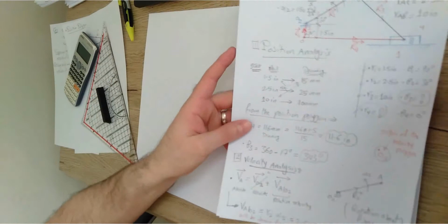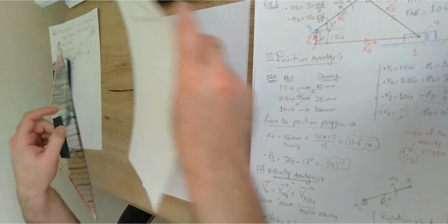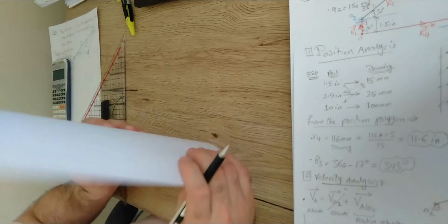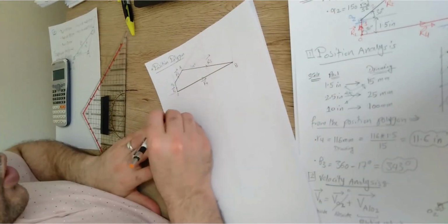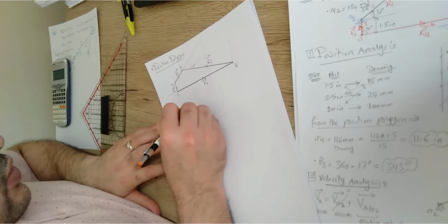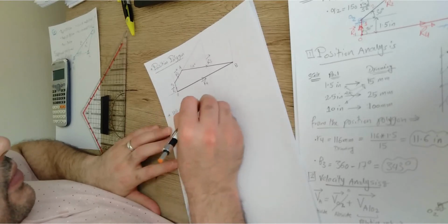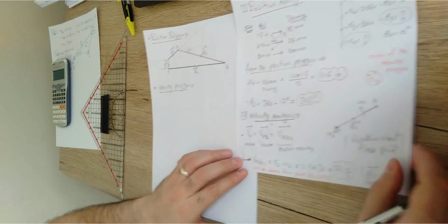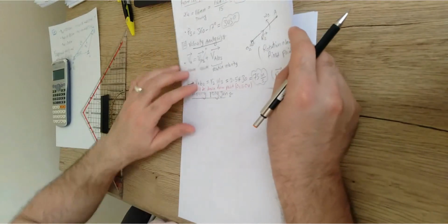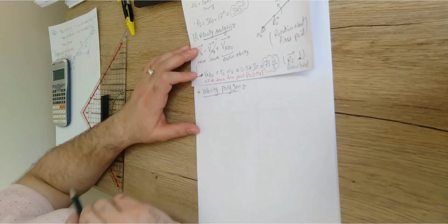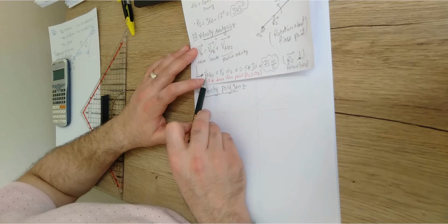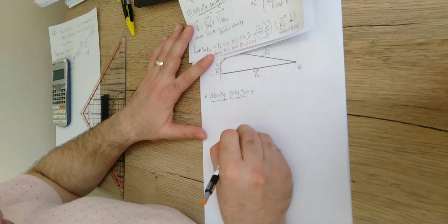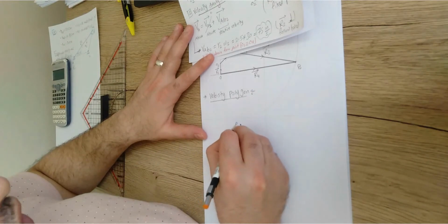Now I'm going to move. After I put this plan, I'm going to bring the drawing sheet to work over it. So the next step is just working over the velocity polygon. I'm going to start reading each one of these data, or the plan that I made here, starting with this relative velocity. If you just read, it would be drawn from either point O or point O2. But the first thing that you have to do is locate a point, which is point OV. Assume that this is point OV.